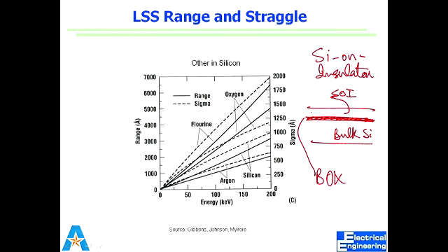So, you guys have seen wafers now. Right? If you hold a silicon or SOI wafer, you won't be able to tell because the oxide is embedded below. And we know that we can't do too deep of implantations. It's about 2000 angstrom deep, 200 nanometer deep. Then we can define how thick of a box we need, right?